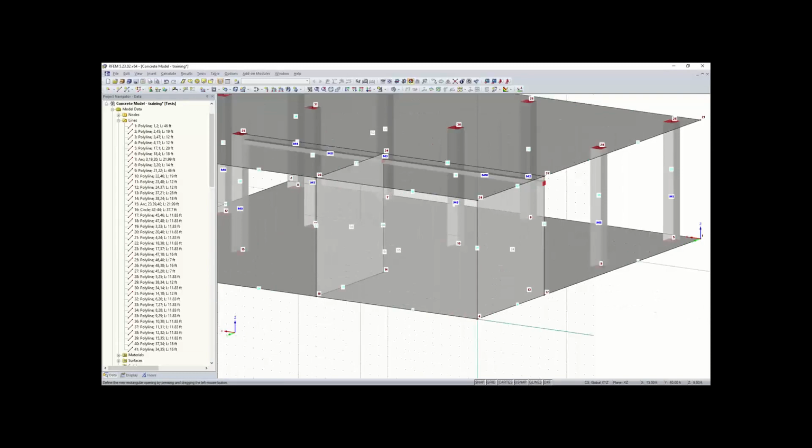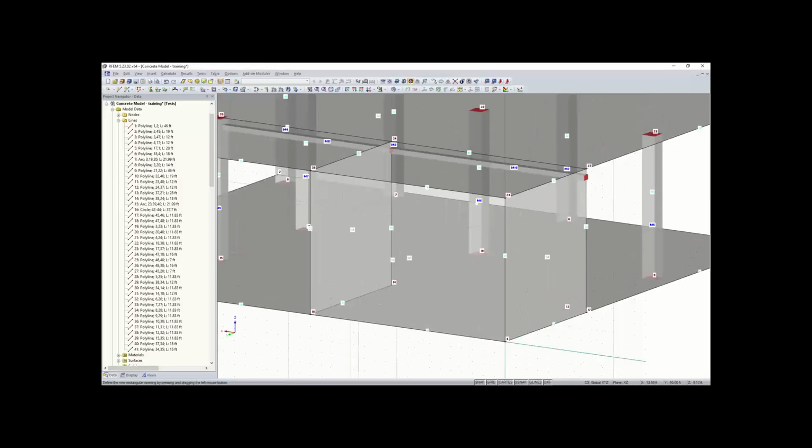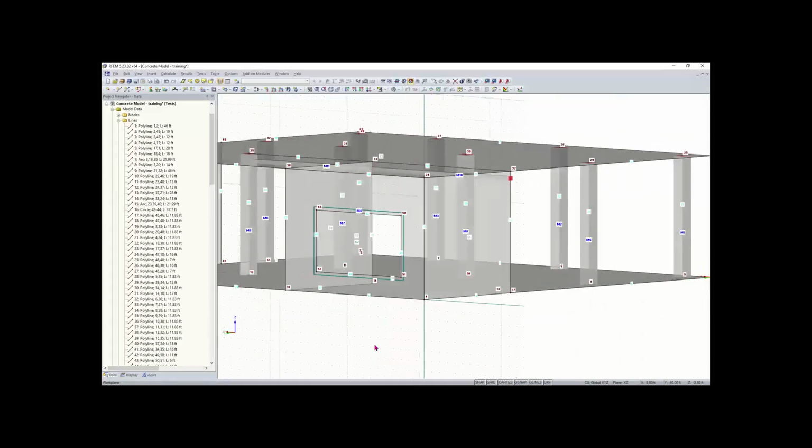And that's going to start at the top left here at the coordinates 1408. We can snap to grid points right here. And then we can just simply draw that. And that's going to end at 503 right there. And now our opening has been created, our back window there.